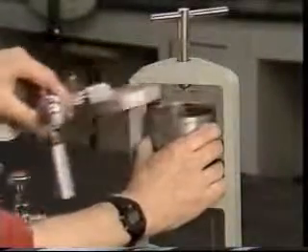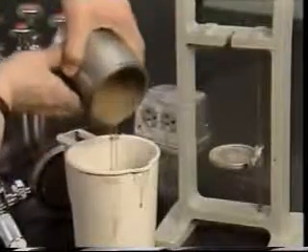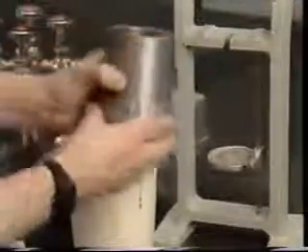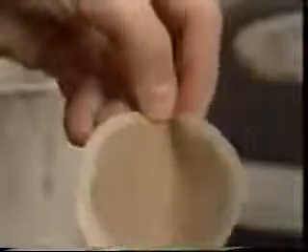The pressure is bled off the cell and the cell removed from the frame. The mud is carefully poured out and the bottom cap removed. This cap is then turned upside down on a solid surface and the filter paper removed. After a light rinse with water, the thickness and consistency of the filter cake can be recorded. The press is then carefully washed, dried, and reassembled for storage. Filter paper is not stored in the press. The amount of filtrate is reported, as is the filter cake thickness to the nearest 1/32 of an inch.